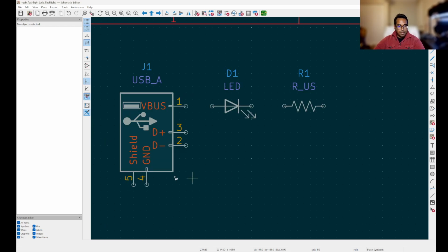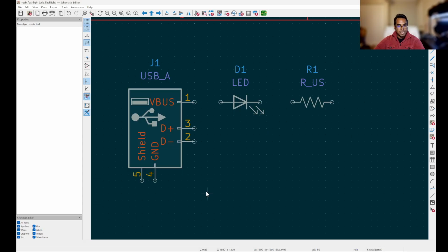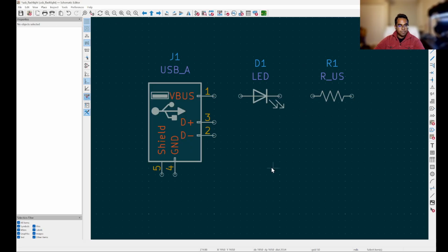Now, there are a couple of different ways for us to connect this ground to every other ground in our circuit, but we tend to gravitate towards one more than the other. The first option is to draw a line from every ground and connect them to each other. For instance, say we wanted to have both the LED and the resistor connected to ground at the same time.